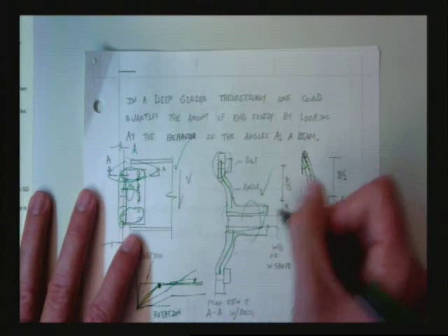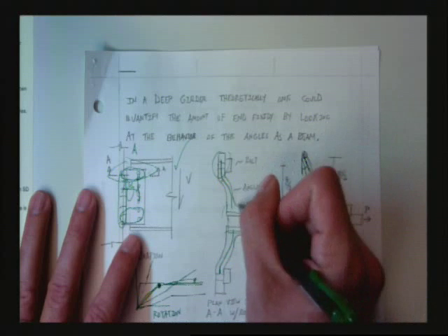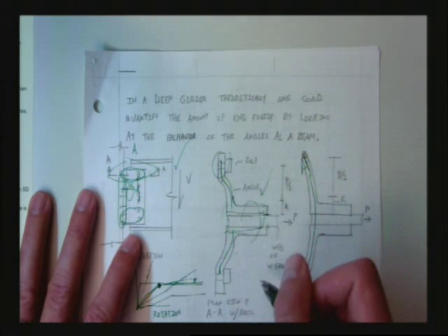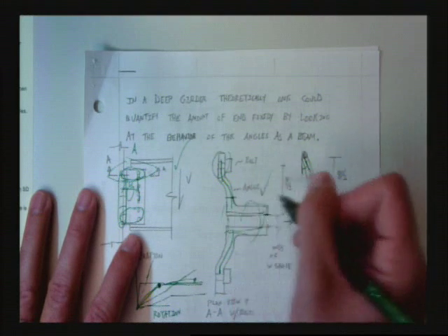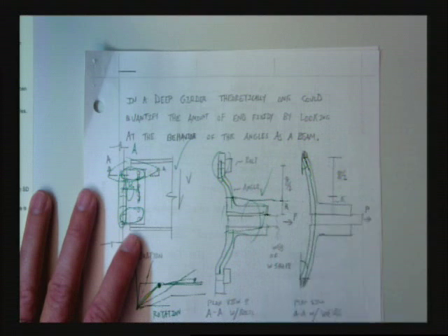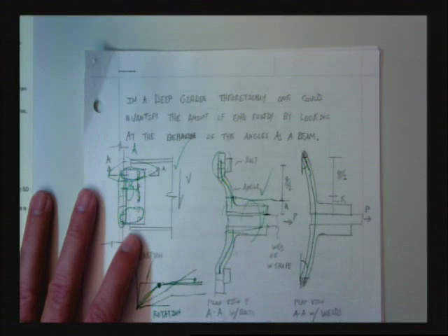That's not exactly the angle thickness. It is actually the depth from the edge of the angle to the end of the chamfer. That's what we call the K distance. Okay? That's what we call the K distance.